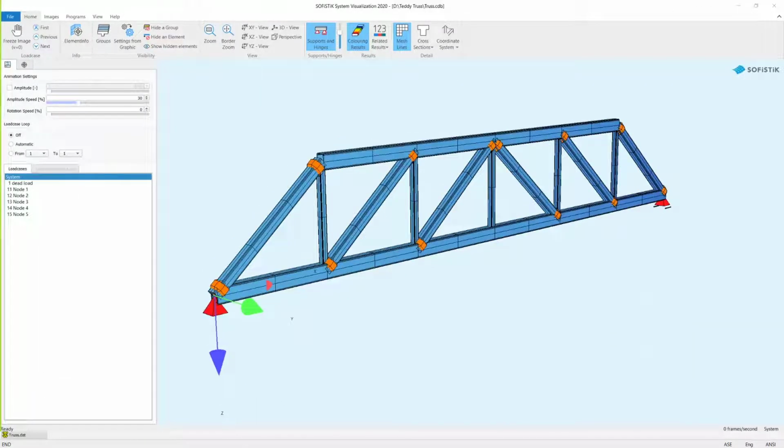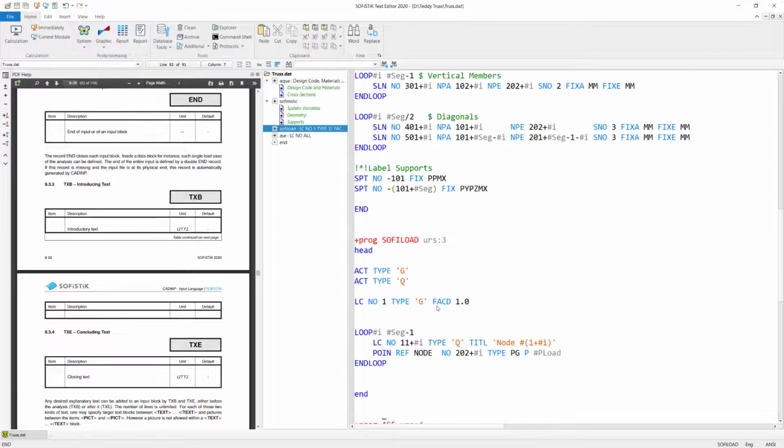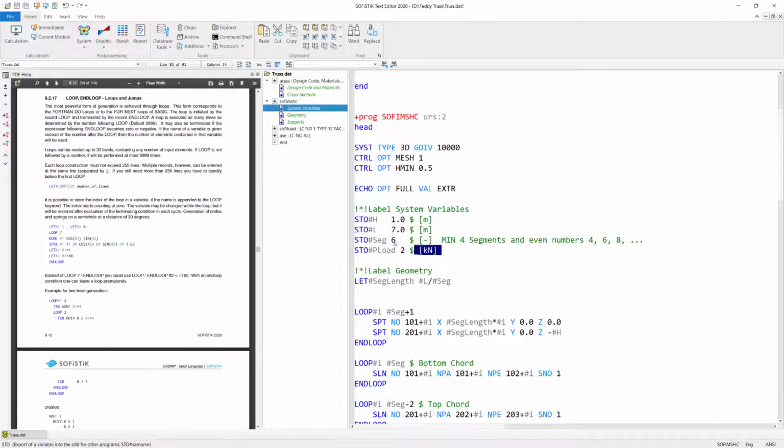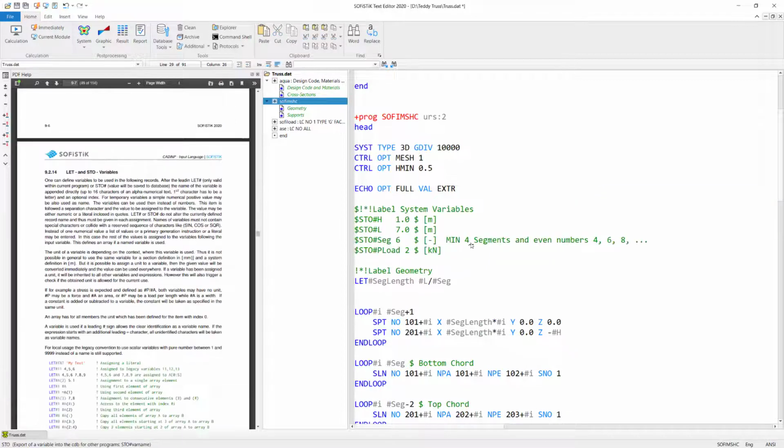Okay, with the calculation done, and yeah, kind of checked all the inputs in SOFiSTiK graphic. Let's do one more last thing before we conclude the session over here. And this is simply cutting out this input, bring it to the very top. So actually that the user don't need to browse through the script to actually find a particular position where to enter information and tweak actually the system. So what I do is I use the copy paste command. So Control C and also Alt C, which comments out the entire selected block.